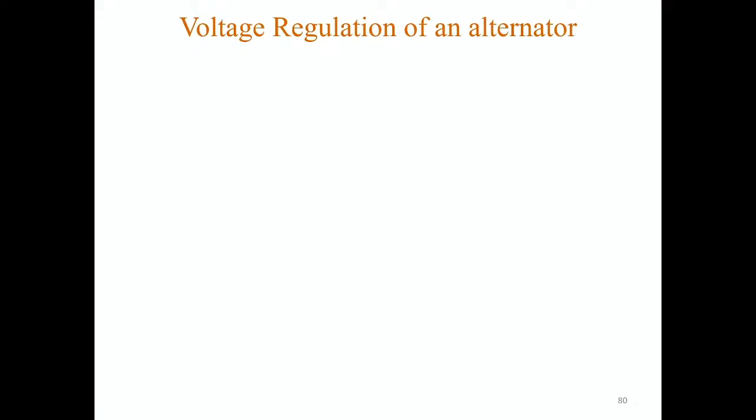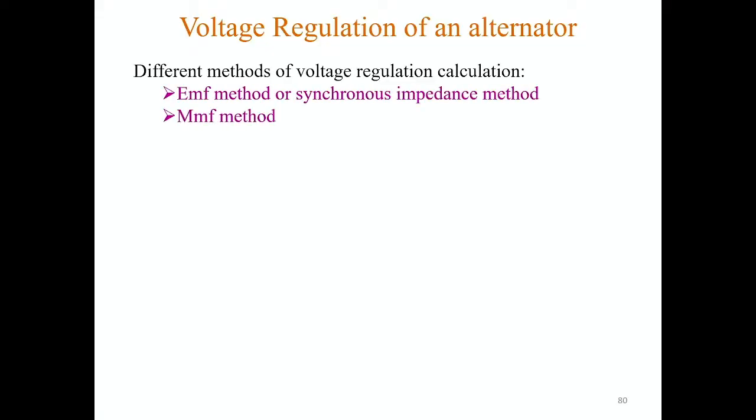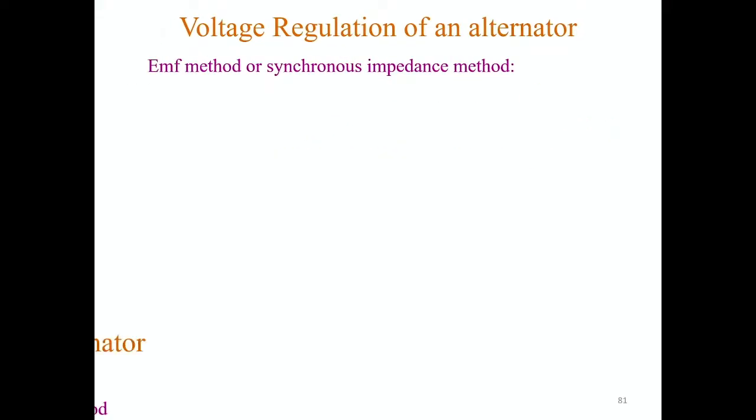So next is voltage regulation calculation. Actually, voltage regulation we have defined already. So there are three methods here we will consider. First one is the EMF method or synchronous impedance method.